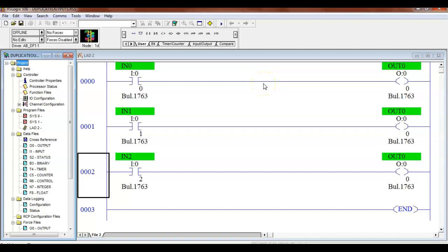So you're down here, you're hitting an input, and it looks like the rung's supposed to be true, but the output never goes true. Well, what could be the problem? You're using that same output somewhere else in your program that's in a smaller line. And this happens every once in a while in this class. I've seen it happen more than once where people duplicate outputs. So we can't duplicate outputs, right? You understand that. The problem is, though, when we check it, it don't give us an error. Because technically, the rung's in the right syntax.